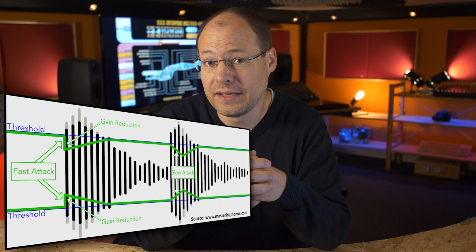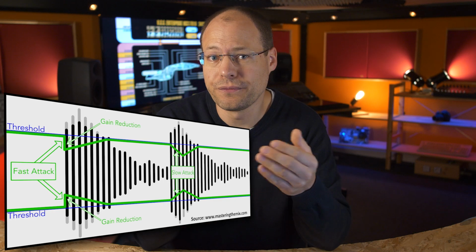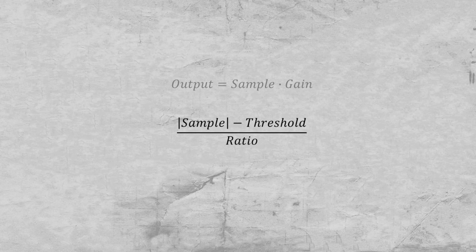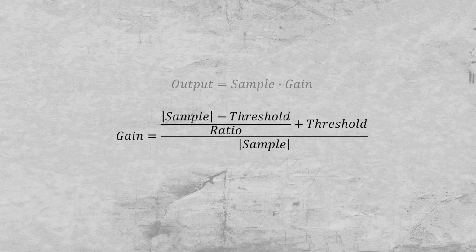Well, first of all, the ability to set the volume automatically, meaning another multiplication for at least 24 bits. To calculate the gain, we first need to compare the absolute value of the audio signal with a given threshold signal and calculate the overshoot. This overshoot is then used as the base for the necessary compression and results in the desired gain normalized to the sample. Unfortunately, there is now a crucial difference to the equalizer if we look at the equation.